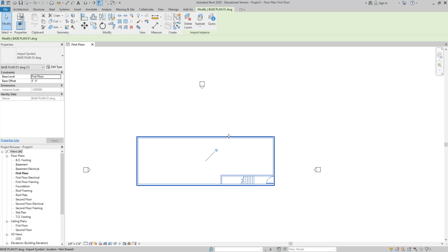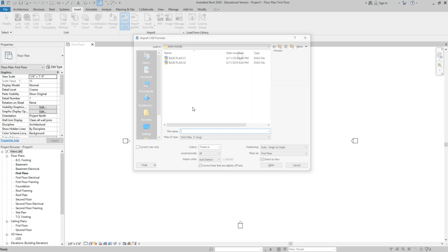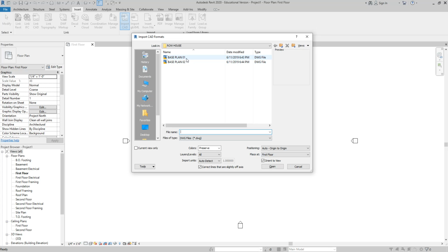If they X-referenced everything correctly, then if I reference in the first floor and just do everything automatically, my second floor plan should go in without a hitch. Whereas if I drag the first floor plan in, the second floor is still going to go over here, and then I have to move the second floor. Do you guys see what I mean by that? You always run that risk that whoever did your plan might not have done it right in the first place, so you just have to be careful about that. And we can always fix that, and we'll check it.